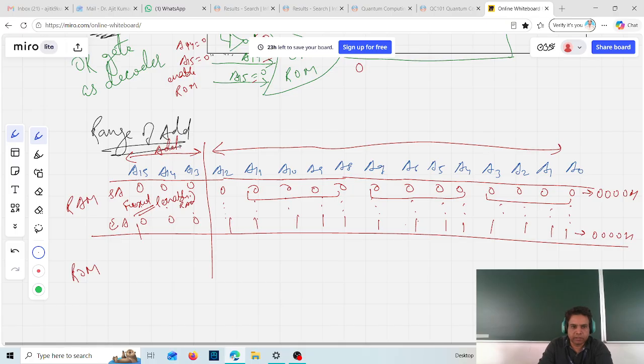And then you see here this 0001 is 1. This 1111 is F, this 1111 is F, this 1111 is F. So I will write here quickly 1FFF H. This is the end address and this is the starting address. So this is the range of address for the RAM.